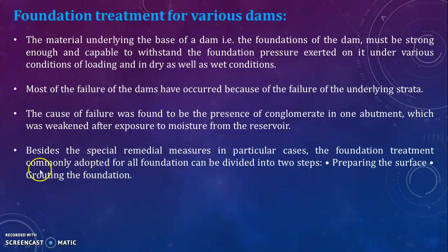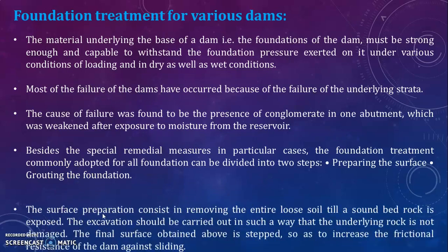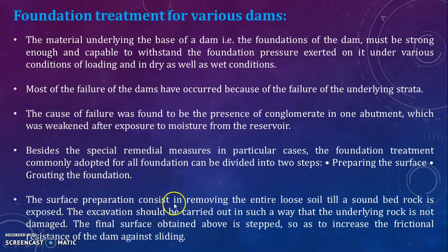Besides the special remedial measures in particular cases, the foundation treatment commonly adopted for all foundations can be divided into two steps. The first one is preparing the surface, the second one is grouting the foundation. The surface preparation consists in removing the entire loose soil till a sound bedrock is exposed.